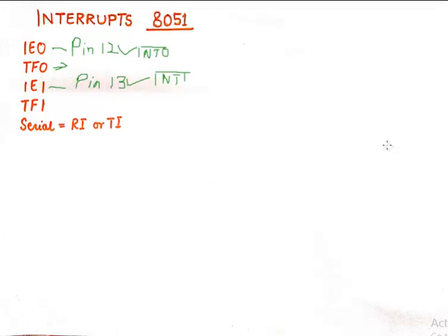and you'll find this interrupt in the TCON register of the timers also. I'll put a reference of the TCON register here. So you need to refer to the TCON register once again. The 7th and the 5th bit of the TCON register are the timer overflow 1 and timer overflow 0 flags respectively. But the idea is pretty clear.